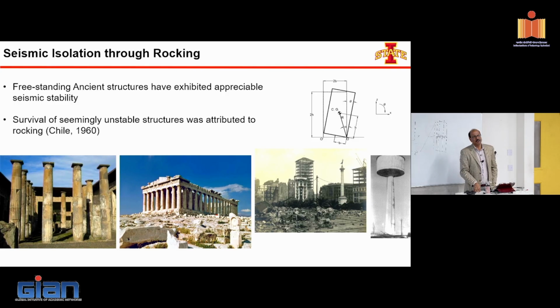So one of the things we investigated for single rocking wall was to put a rubber interface between the foundation and the wall panel. If you do that, you can add another 3%, 4% damping depending on the type of rubber. I think some rubbers can dissipate more energy than some of the other qualities.